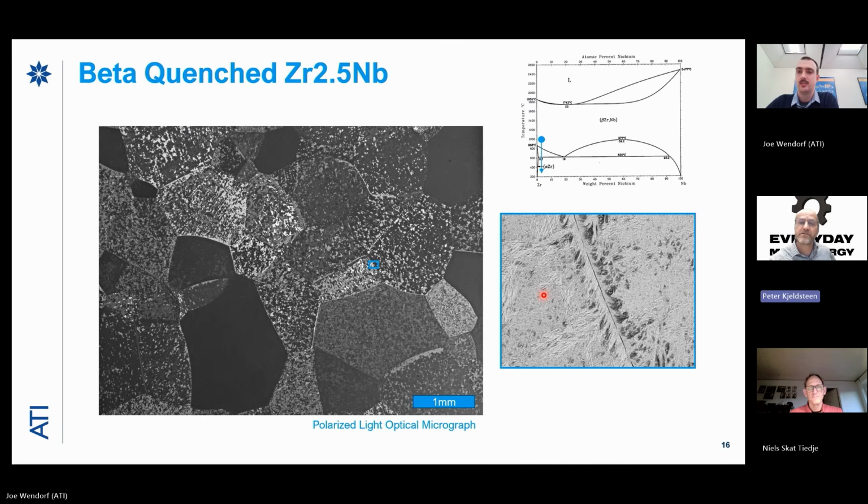Does that precipitate during heating up, or is it not? So what happens when this microstructure is then extruded into a pressure tube, the niobium comes out of supersaturation into beta precipitates.